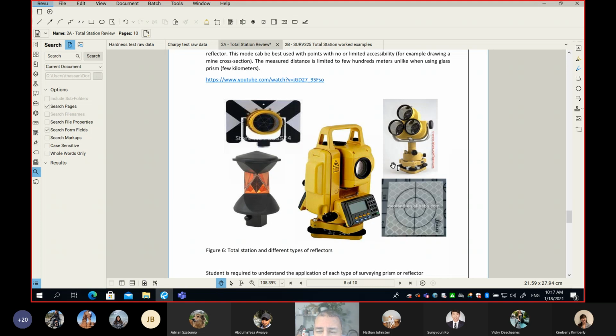I know some of you will question: if I have a single prism, I know where I can shoot. There is a center of the prism, and I can shoot right away at the center of the prism. Now, for the combination of prisms in the picture on the right, where do we shoot? Do we shoot at the center of the prism on the top, or the right, or the left? The answer is you shoot at none of them. You shoot at the center of gravity of the three of them.